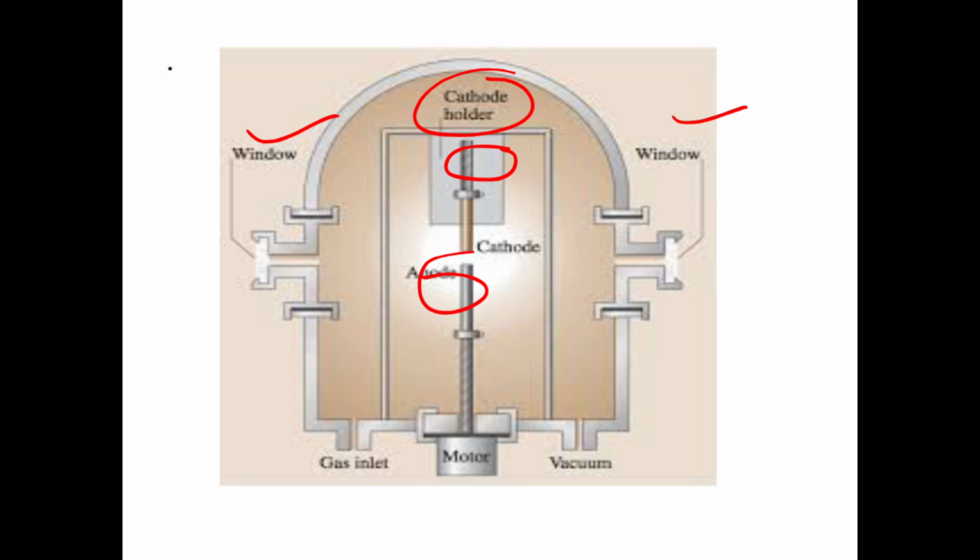So how does this process occur? When we apply DC voltage of 20 to 30 volt, it starts producing an arc like lightning or spark between these two electrodes. First, these two electrodes are not separated, but when we apply voltage, we create the distance between them, so they produce arc. When the distance between them reaches up to 1 millimeter, they stop producing arc, and this has already produced enough arc to heat up the chamber.